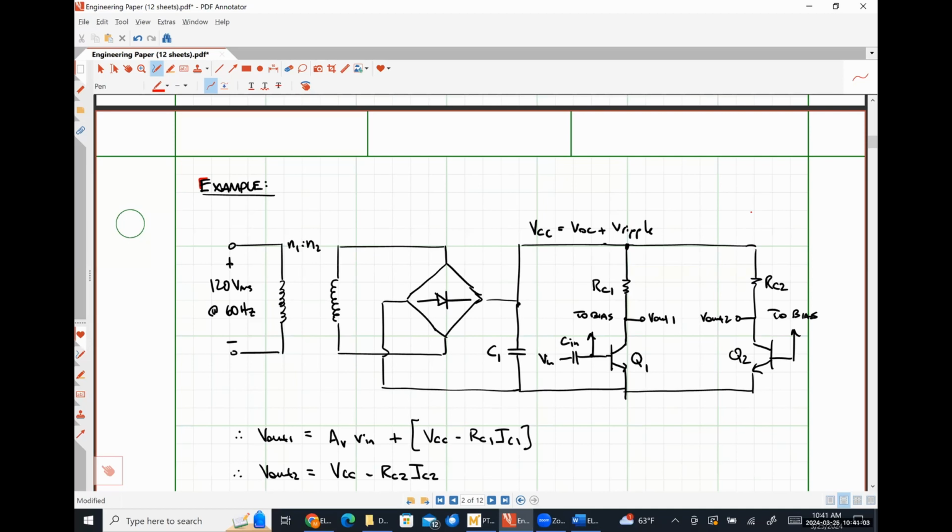It depends on what you mean by the transistors don't work. Realistically, we're just trying to minimize the chance that they get pushed out of the active mode of operation, right? Effectively, that ripple voltage is going to be constantly increasing and decreasing the headroom that our output signal is allowed to occupy.